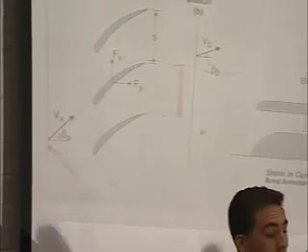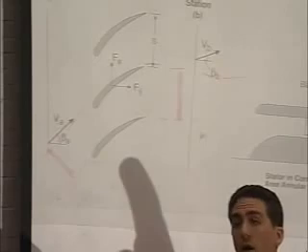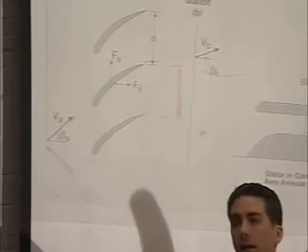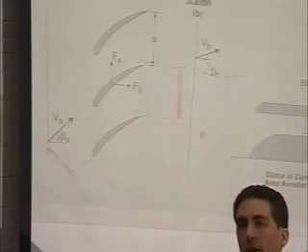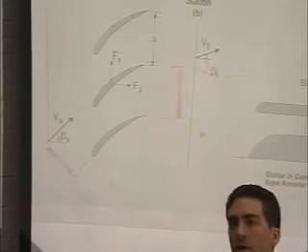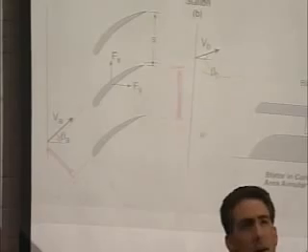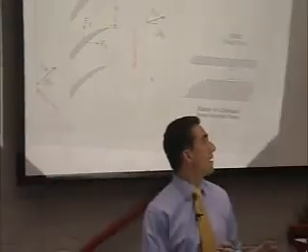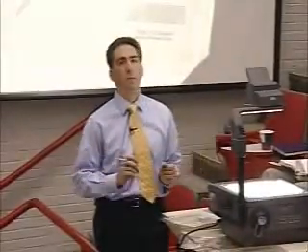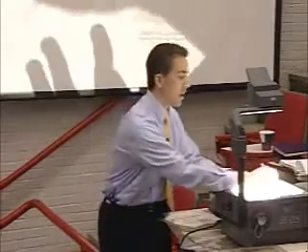So there are forces on these blades. There are torques, but they're not moving. So they don't do any work. They just take one kind of energy and turn it into another. Is that okay? Conceptually, you have to really be able to unwrap the compressor. So flow in this direction is tangential. Flow in this direction is axial.